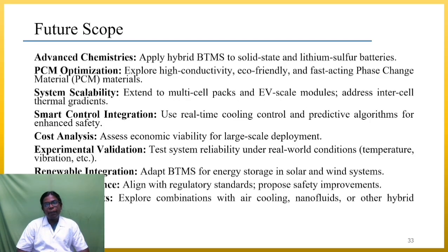Future scope: apply hybrid BTMS to solid state and lithium sulfur batteries. PCM optimization: explore high conductivity, eco-friendly and fast acting PCM materials. System scalability: extend to multi-cell pack and EV scale modules, addressing inter-cell thermal gradient. Smart control integration: use real-time cooling control and predictive algorithms for enhanced safety. Cost analysis: assess economic viability for large-scale deployment.